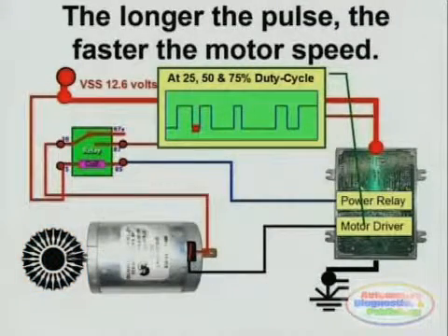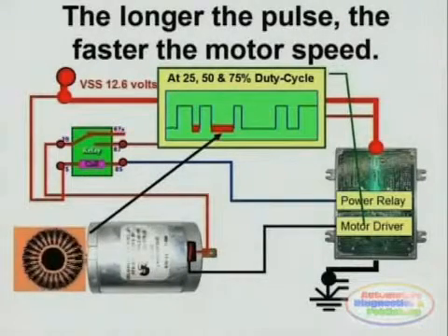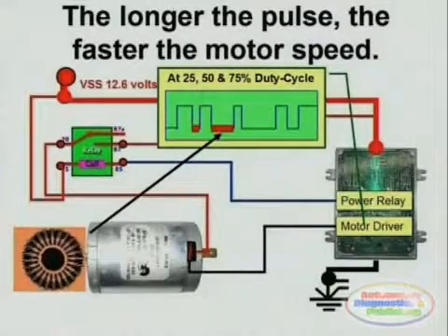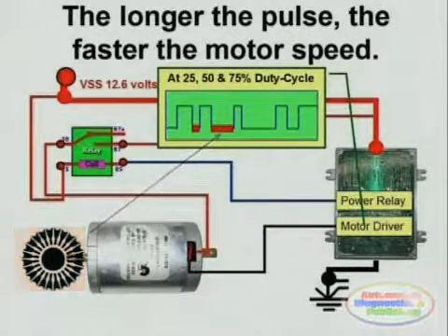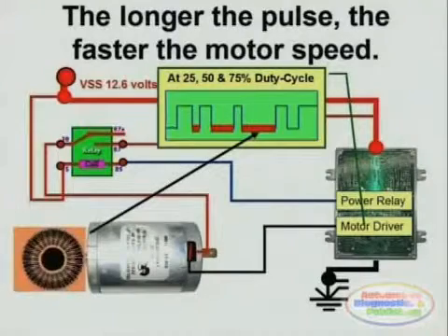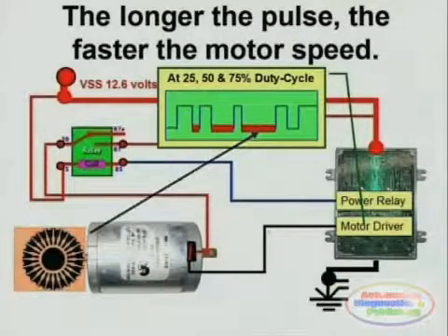Next, we see how the duty cycle increases and the motor turns faster. Remember that this is a repeatable wider pulse, and it is not repeated here in this diagram for the sake of explanation. But the longer the pulse, and now we can see that the fuel pump is turning even faster. The longer the pulse, the more work the component is going to perform.